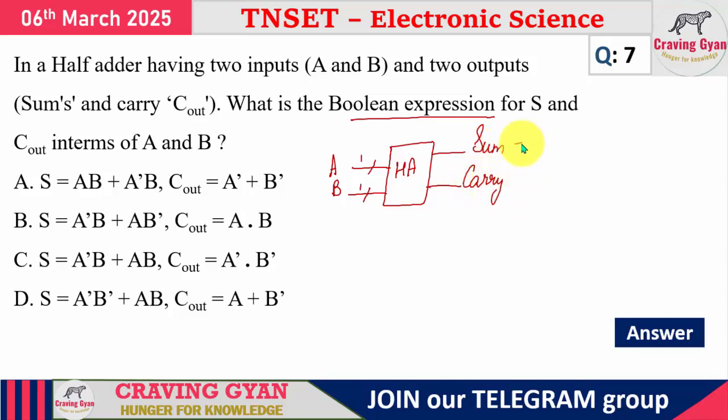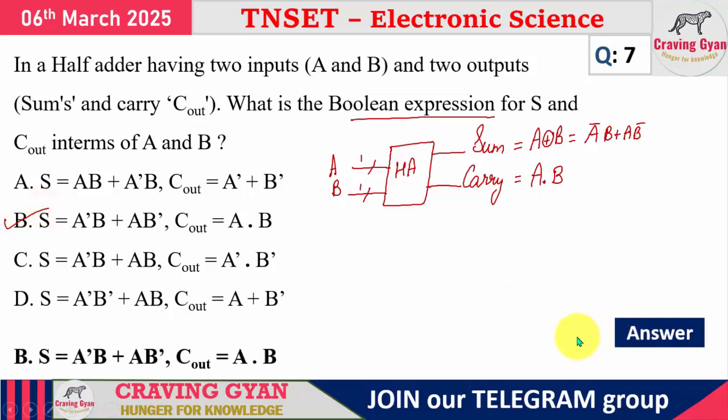The expression for sum is A XOR B, which is equal to A bar B plus A B bar. Similarly, the carry expression is A into B. The corresponding option that is going to follow is option B is correct.